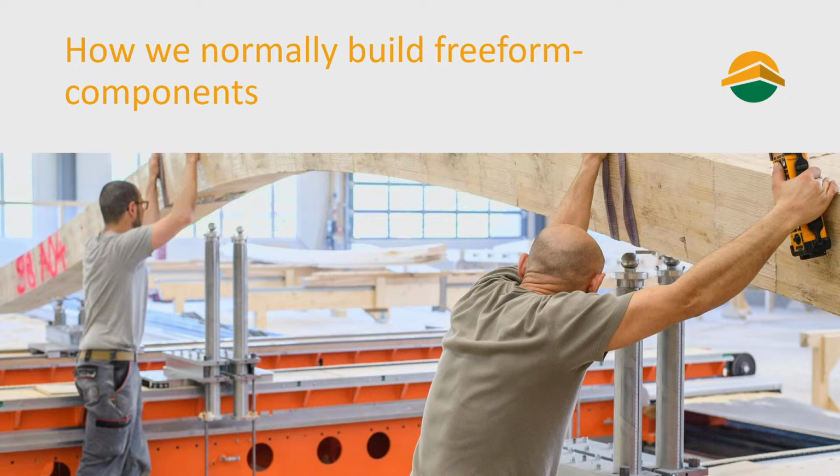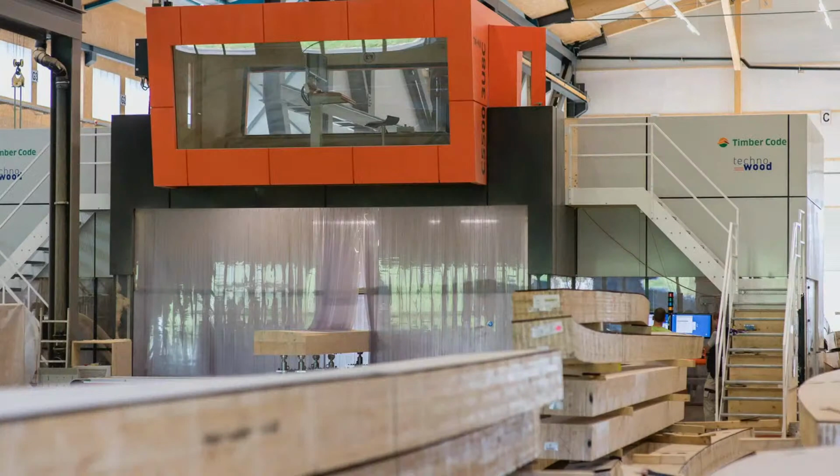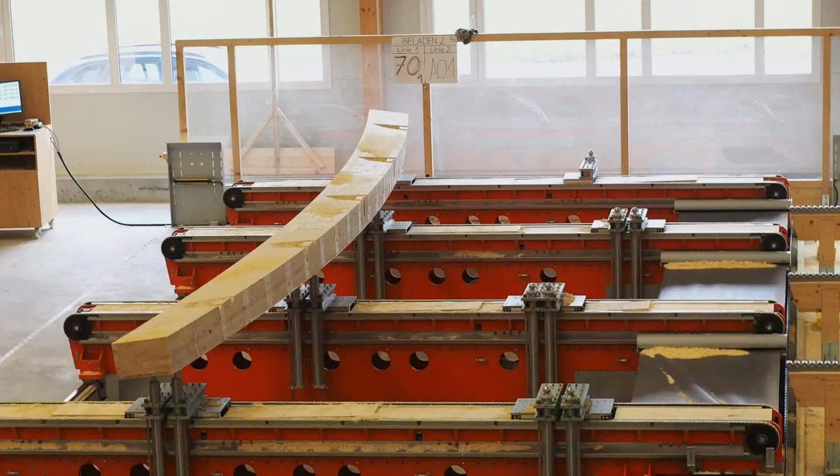Short explication how we normally are used to build freeform components. So we are used to produce blanks out of glulam. They could be straight, doubly curved, single curved. They are then milled on the CNC machine on all sides to obtain a very good accuracy and a good quality of the surface. Here you see the heart of our CNC center. With our CNC machine, we mill pieces with a length of up to 30 meters, 5.4 meters large, 1.8 high.